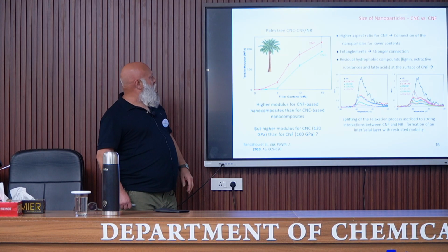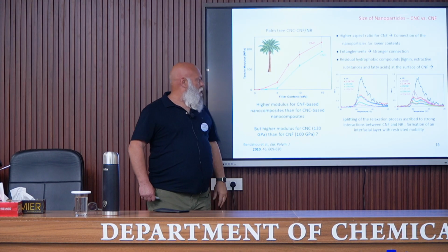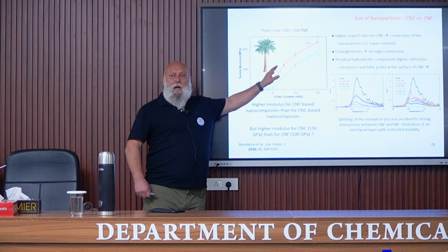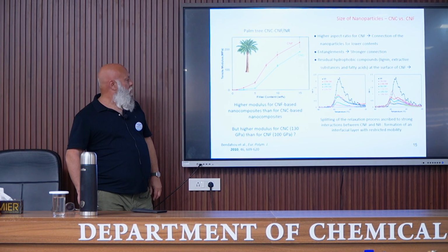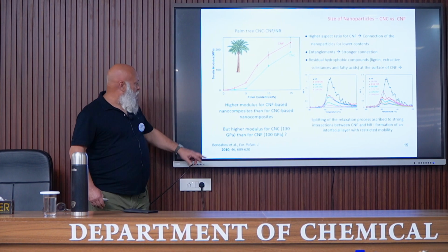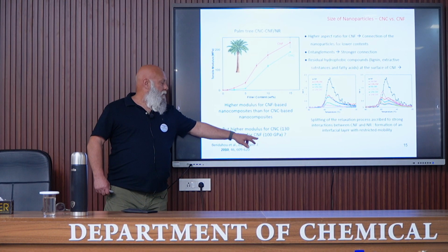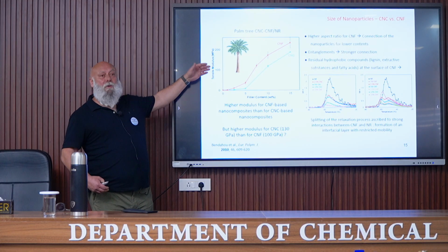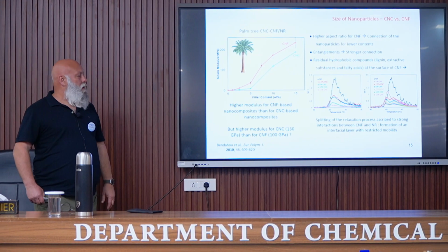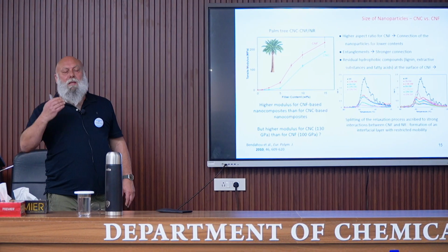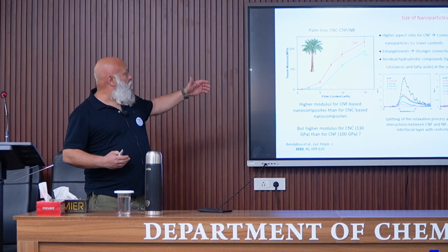This is the evolution of the tensile modulus for both types of nanocomposite as a function of filler content. We can see that a higher modulus is observed for nanocomposite based on nanofibril, which was not really expected. Remember that the modulus of nanocrystals is 130 gigapascal. For nanofibril, it's lower, and the reinforcing effect is higher. So, in such a situation, you have to think about what can be the parameters that can lead to this result.